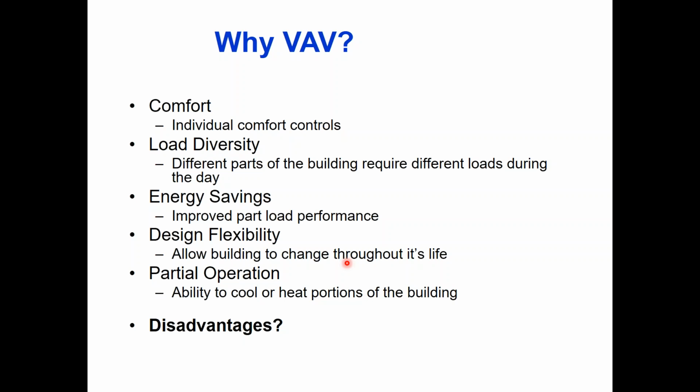So if I needed a 50-ton air handler, that's how big the air handling system was that I was going to put in. Now I'm only going to put a 40-ton air handler in instead of putting the 50 in. I'm going to bank on the fact that all the zones are not fully open at the same time. They may be partially open at the same time. 2 or 3 may be fully open while a bunch of other ones are partially open. But the chance of every single space being open 100% means that somehow the sun is magically shining on both the east and west sides of the building at the exact same moment, and every single person has shown up to the building. I'm going to bank on the fact that that doesn't happen and size the equipment smaller.